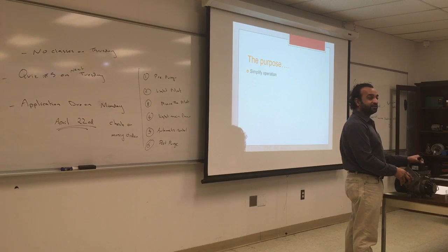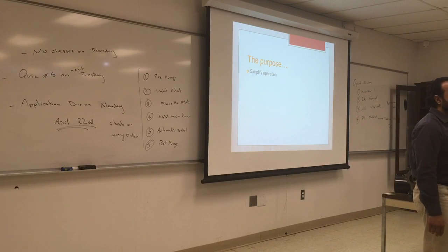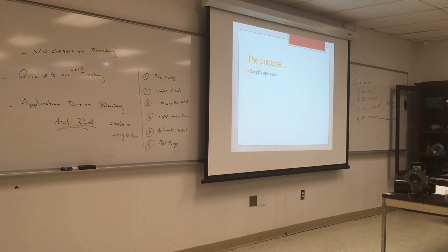How do you change the firing rate? By hand. You have to go and change the nozzle. So a lot of things are done manually. How do you change the pressure? Again, by a screwdriver. So a lot of things are done manually, and they are set at one single firing rate. In commercial, we can do all these things remotely, and we don't have to go and interact with the equipment. So, we want to simplify the operation.